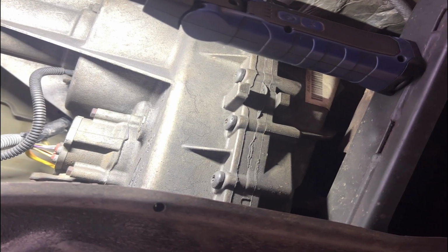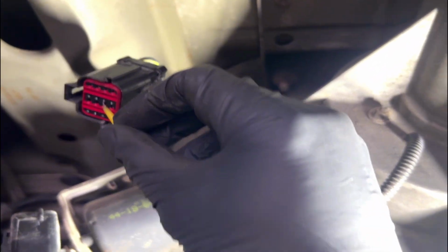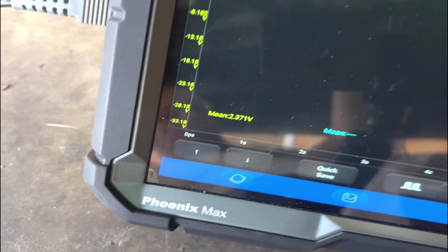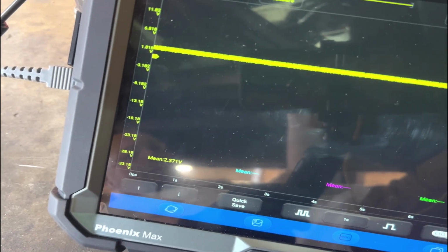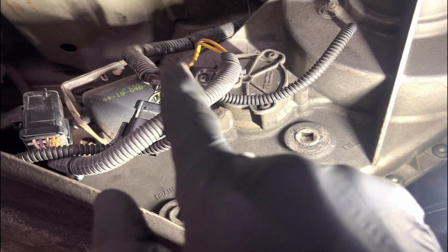So now these are pretty cavernous. Those are like the big round circle plugs. So we're in there for sure. And we're at 2.3 volts. And so it seems like the transfer case control module is putting out 2.3 volts. And we're getting a 12 volt feedback through this motor somehow. That is very strange. Let's see if it'll carry current. I know that this camera works probably terrible because I'm underneath this car.